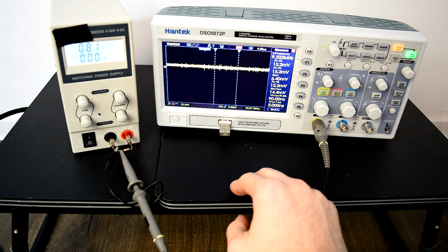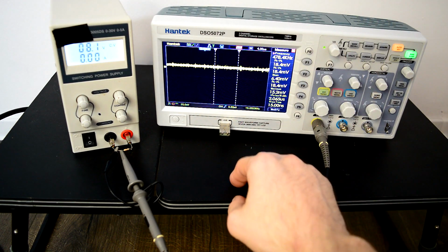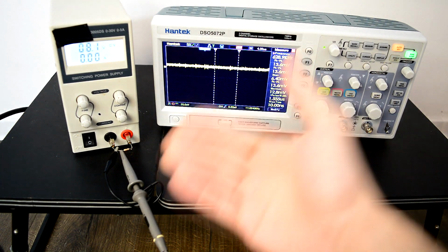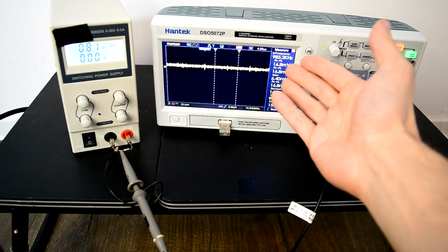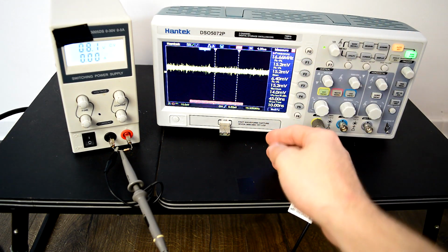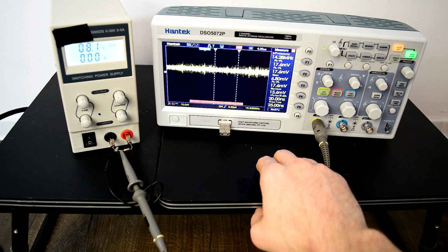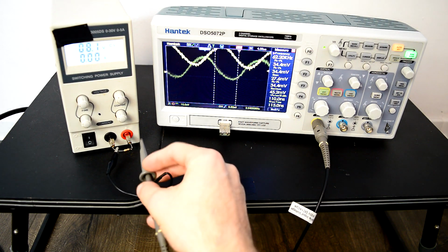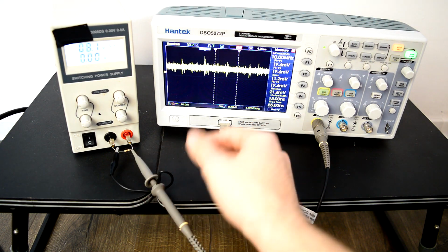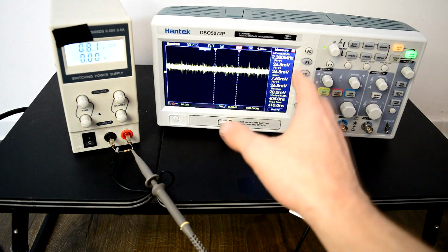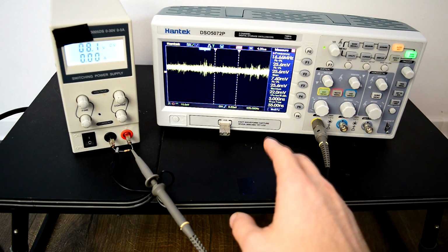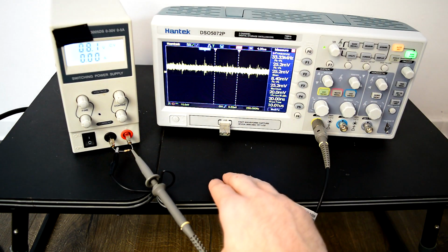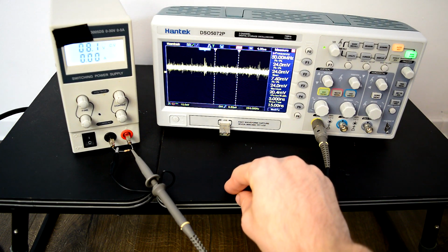What this is telling us is that the 400 kHz noise has something to do with the earth ground. Because by removing the earth ground, we're left with only around 15-16 millivolts of noise, so quite decent. And if I now measure the differential noise, the noise between the outputs of the supply, we get the same 26 something millivolts. So the supply is not that bad. Its differential noise is quite small, it's just that the common mode noise is large.